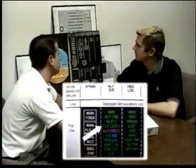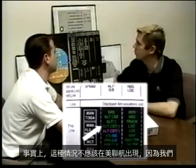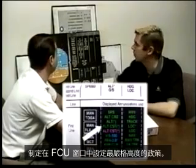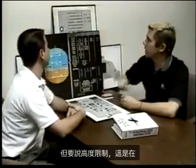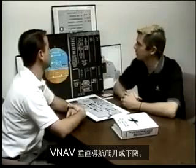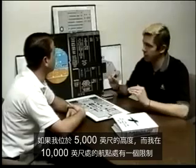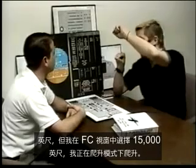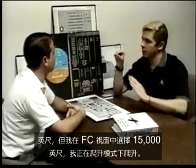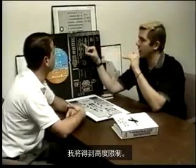ALT CST. ALT CST is rarely seen at United. As a matter of fact, it shouldn't be seen at United because we have a policy of setting the most restrictive altitude in the FCU window. But to talk about altitude constraint, this is used during a VNAV climb or descent. Let's just talk about climb mode because it's an easy one to start with. If I'm at 5,000 feet and I have a constraint at a waypoint of 10,000 feet, but I select 15,000 feet in my FCU window, I'm climbing in climb mode. When I get to 10,000 feet, it will level at 10,000 feet and I'll get altitude constraint.